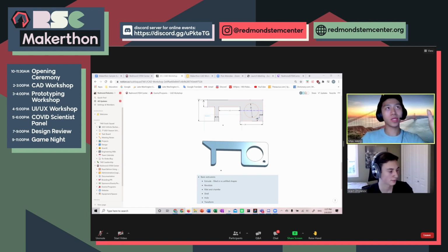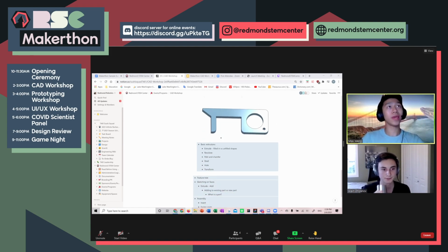What I'm going to do now is use some of the tools that exist in the 3D modeling environment in the 3D Part Studio. The first one that I want to use is the Extrude Tool. The Extrude Tool is, I think, the most basic tool for 3D modeling. It's just turning a 2D shape into a 3D shape, right? Just extruding it outwards.